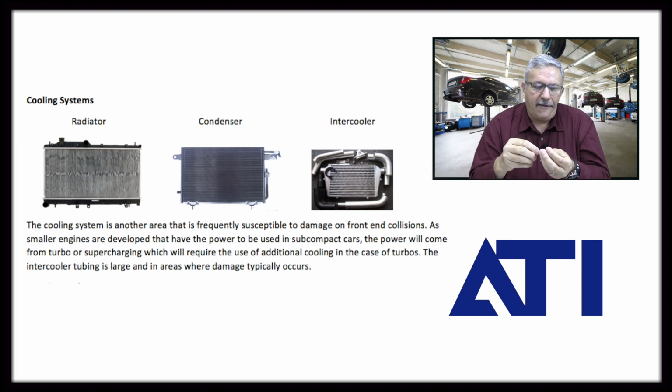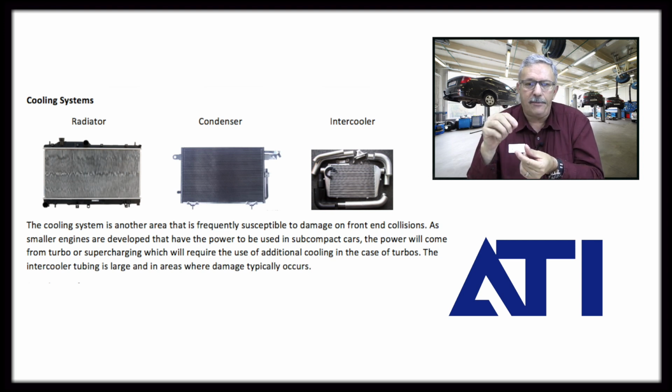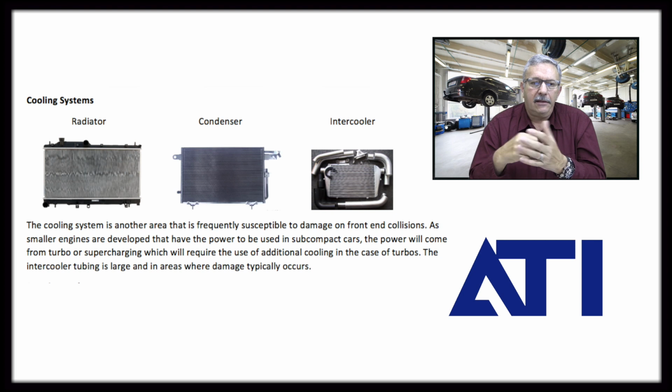So one of the things I have to do is I've got to totally flush that whole air conditioning system in order to make sure that I don't have those little shards of aluminum inside the system. If I don't do that, and there's also some little filters that have to be replaced, etc. If I don't do that, what happens is you go ahead, you put it all back together, everything seems great. A couple months later, a customer comes in and says, hey, my air conditioner locked up. And the cause of that is we didn't take all the contamination out of the system.